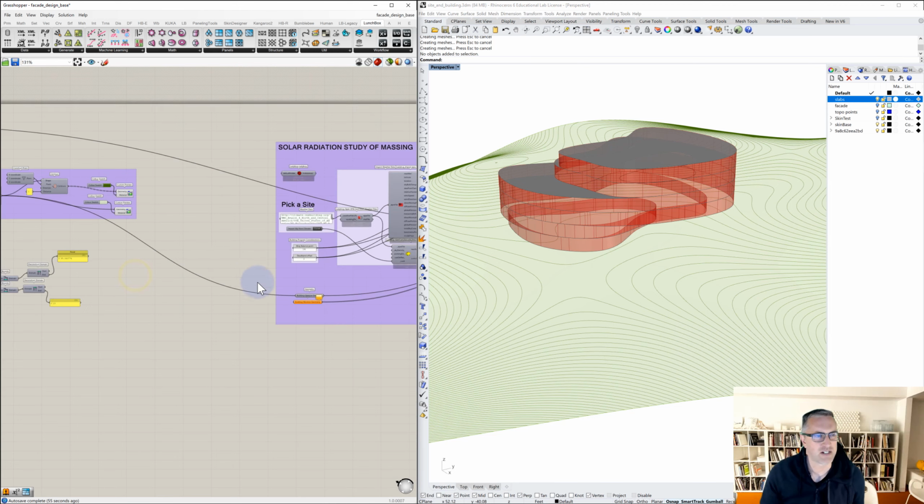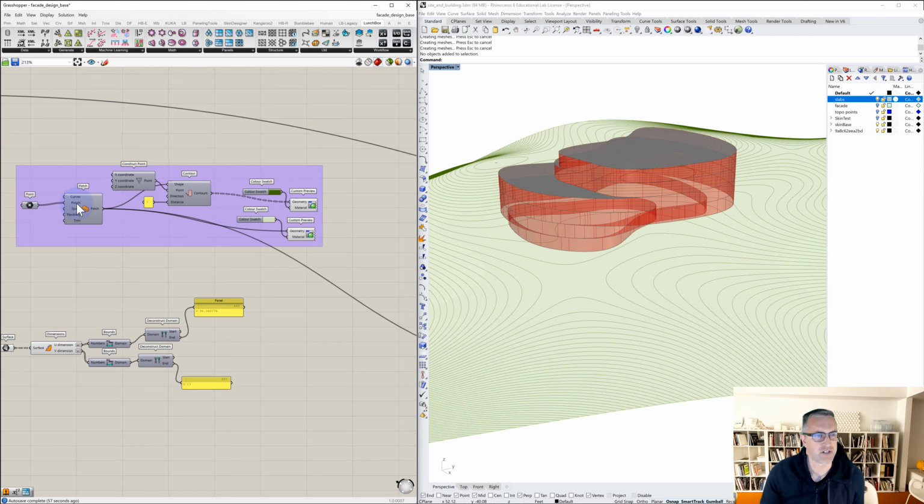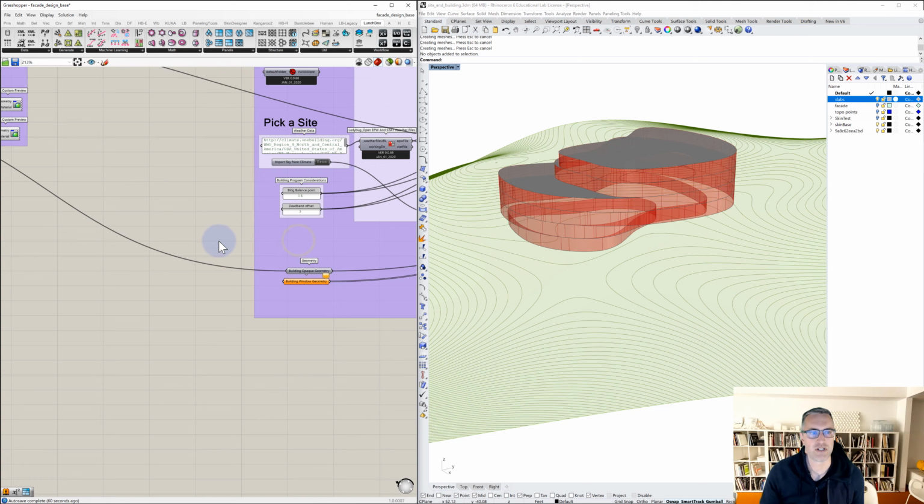And what's coming in currently for the opaque geometry is the topography, but I also want to add a geometry pipeline. And for this, we want to use the slabs. Set this to surfaces, and we'll hold down Control and add this to building opaque geometry.